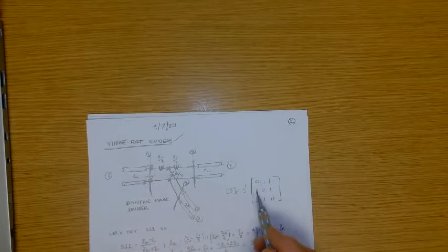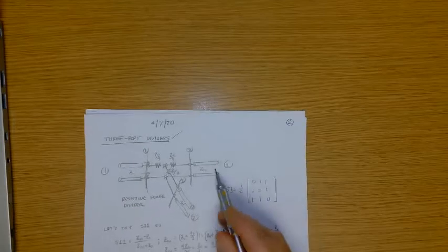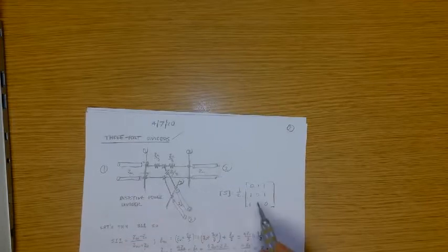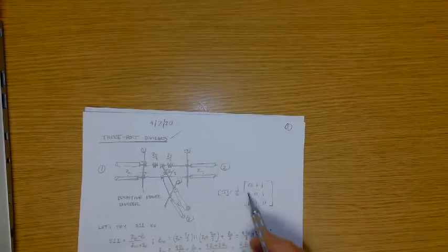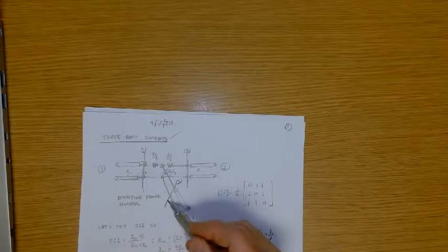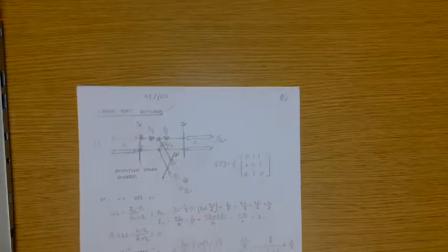And then a half here, a half here. And so that gives you S21, in 1, out 2, so that's a half. S31, in 1, out 3, is a half. So 0, a half, a half. So the wave intensity here is a half, and the power is going to be proportional to the square of that, so it's going to be a fourth. So we're going to see how all that works out in a minute.